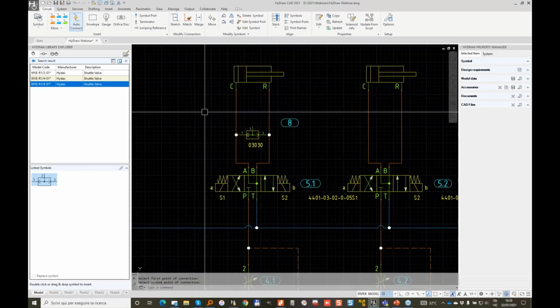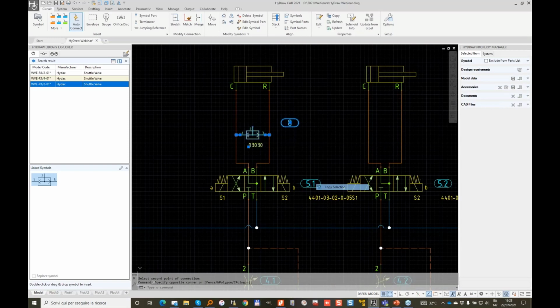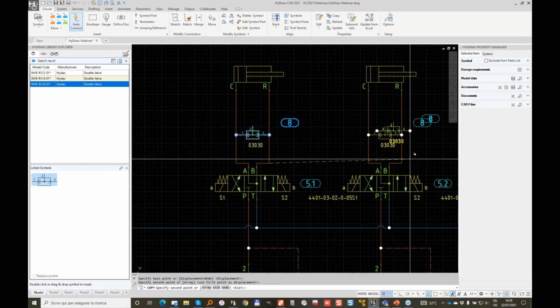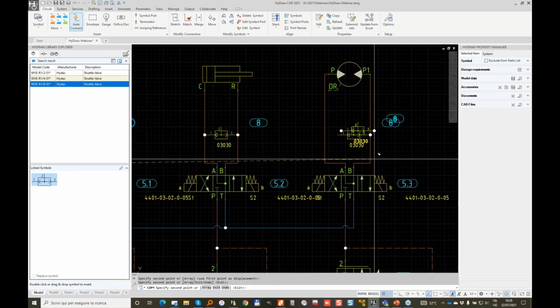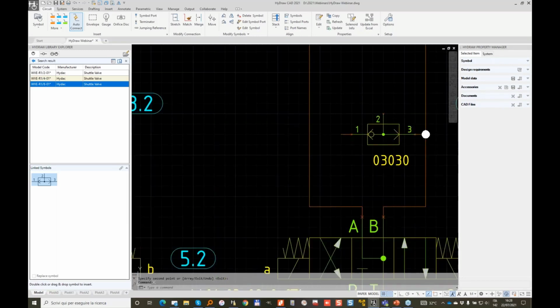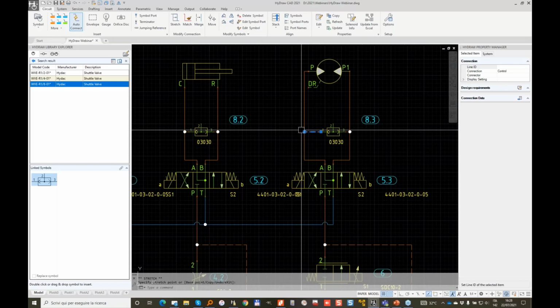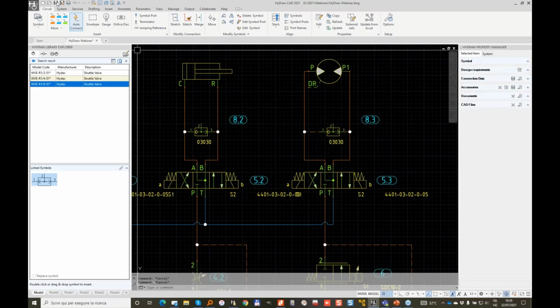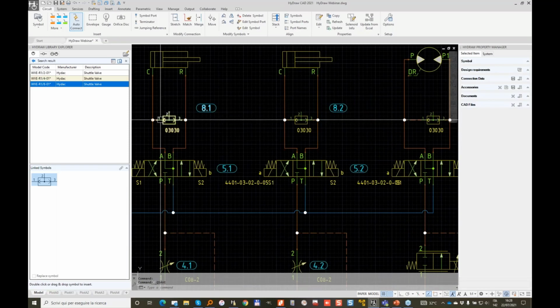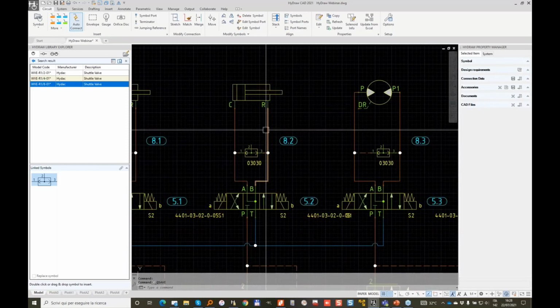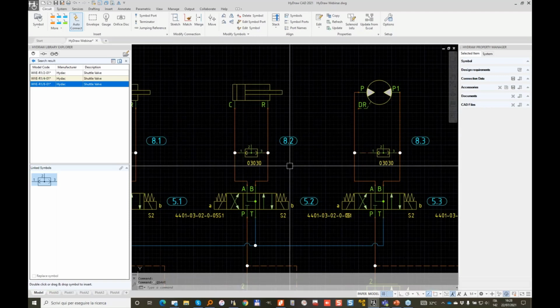So this is my first element. Let me do copy and paste. This connection was not there. Just select the line and position it on top of a connection line. In this case, we are selecting the highest signal from both sections. Now we need to bring the highest between all the three sections.